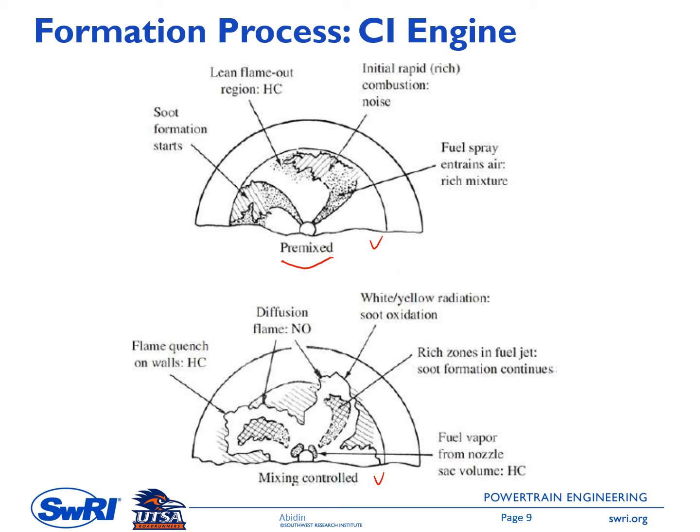In the premix period, there might be soot formation. Okay, it is inside the spray, and then there might also be hydrocarbon formation in the lean flame out region here. There might be noise as well because of the initial rapid combustion, and then because of the huge momentum difference between the spray and surrounding air, there will be an air entrainment inside this spray as well.